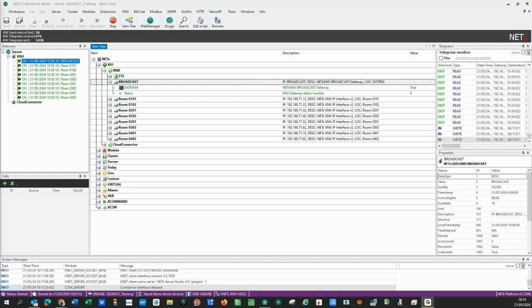It's a hotel, so it's not typical to send a central on or central off to all the rooms, but imagine that it's important to send a central on for the lights, for example. But we have no routing, no communication between the lines. So in terms of KNX, it's impossible to do this. You cannot send from one line a telegram to the rest of the lines.